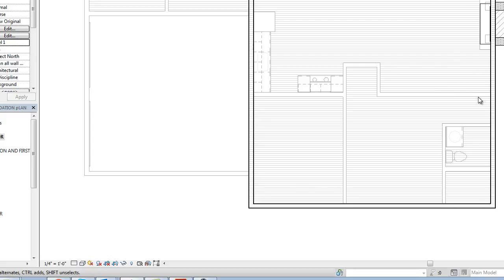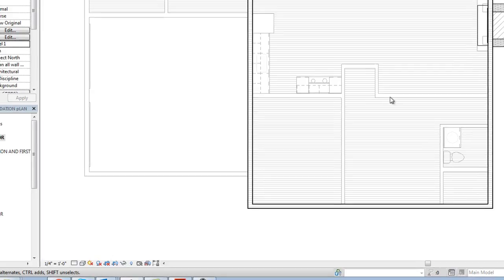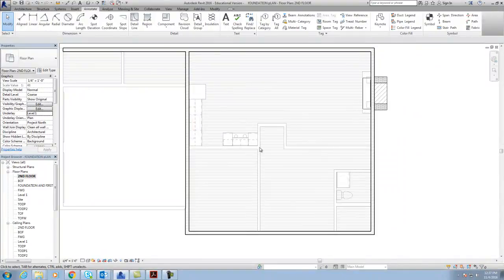Now the reason I could have went with a roof truss all the way across this, on 2-foot centers, and I wouldn't have to have any support in here. All the load bearing would have been on the exterior walls. However, this roof pitch is so steep. It's going to be a 10-12 pitch that they don't make trusses in that high pitch, or not commonly. So we're going to have to build the roof with a support under the middle of it, and this right here will be our support.